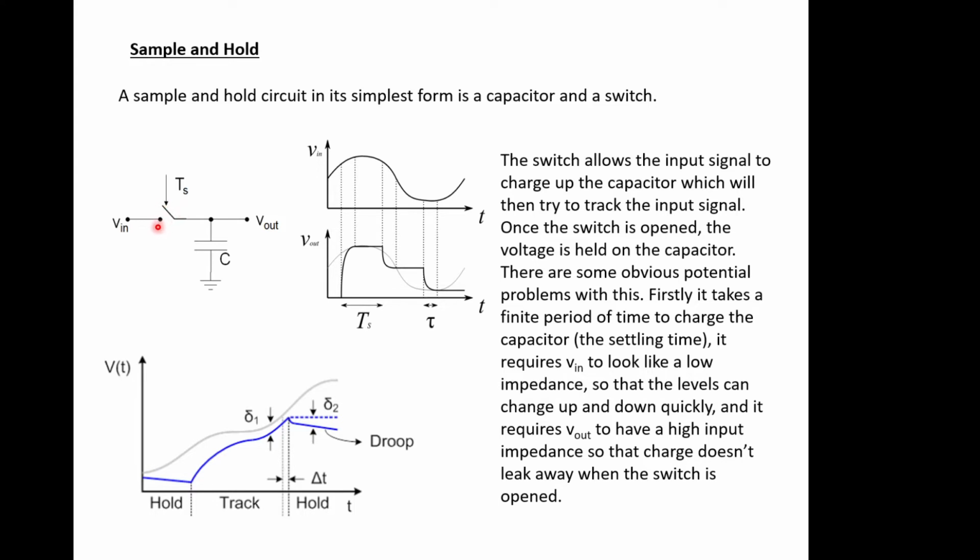That in itself can introduce its own issues, because as it switches, as it charges up, there are going to be little capacitances within the switch itself. Even in a transistor, we have a diffusion layer and junction potentials which need to be charged up. So there's the potential to have an error introduced by this switch as it injects charge into this capacitor. As it opens and closes, it has to charge and discharge itself.